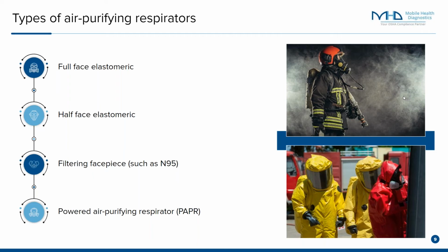And then one other thing to keep in mind is if you have any question whether a respirator does require a fit test, again, either check with the manufacturer, look at the instruction manual that comes with the respirators, or consult a safety professional that can help guide you as to whether a fit test is actually required or not.